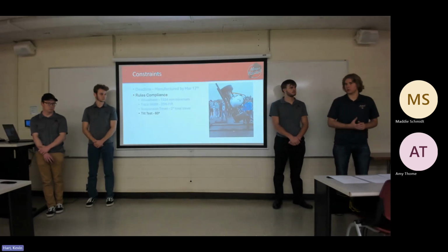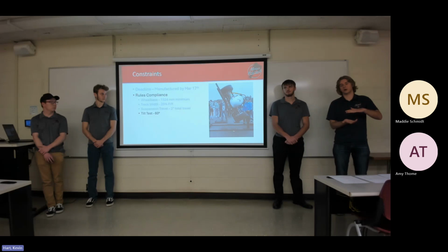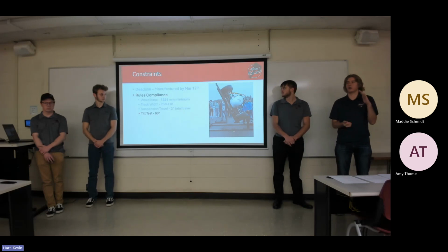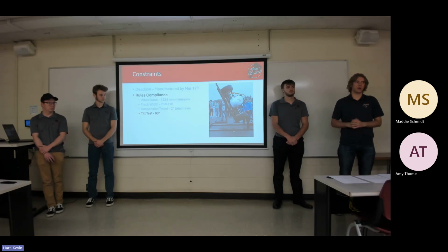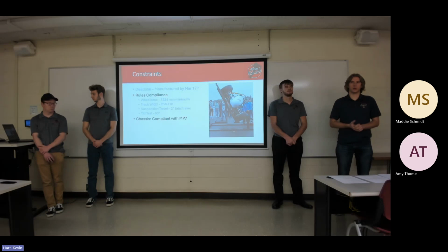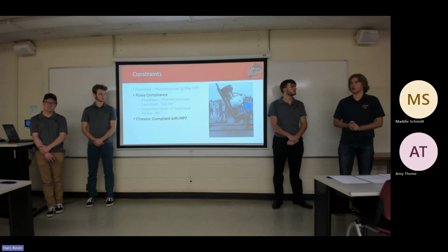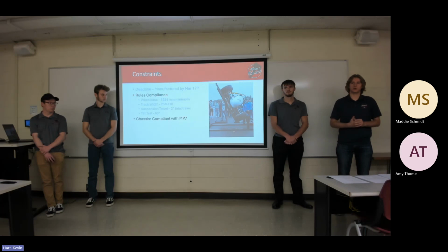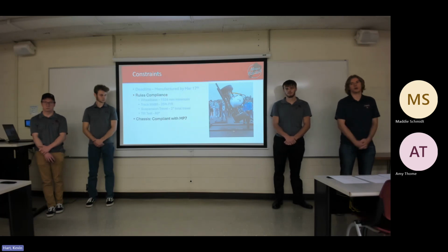So here's a good picture of what the tilt test entails. The car sits on a tilt bed and it gets tilted up, and it has to not tip over at a minimum of 60 degrees. So we need to ensure that the car will pass the tilt test. We also need to make sure that our suspension is compliant with the MP7 chassis. This is a new chassis this year, but we still need to make sure that we can actually put our suspension on this chassis.